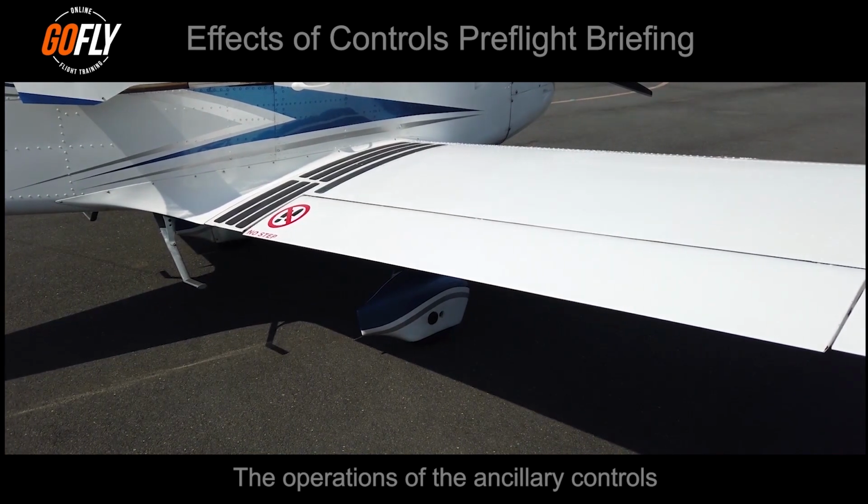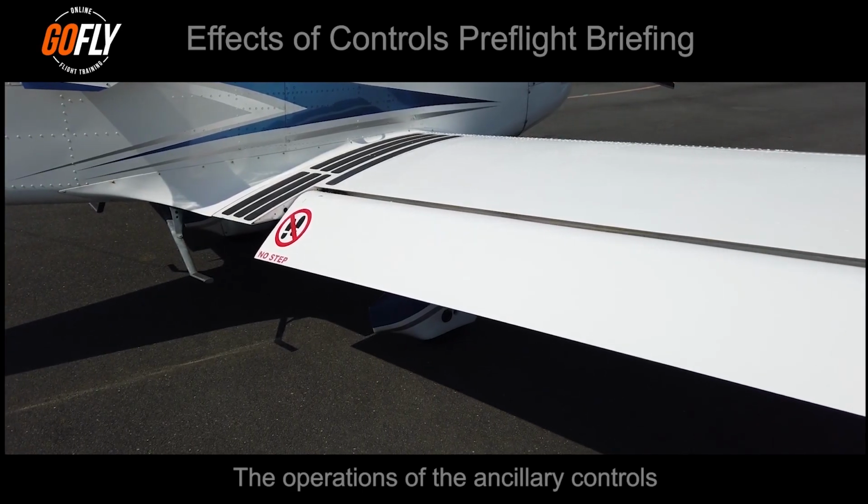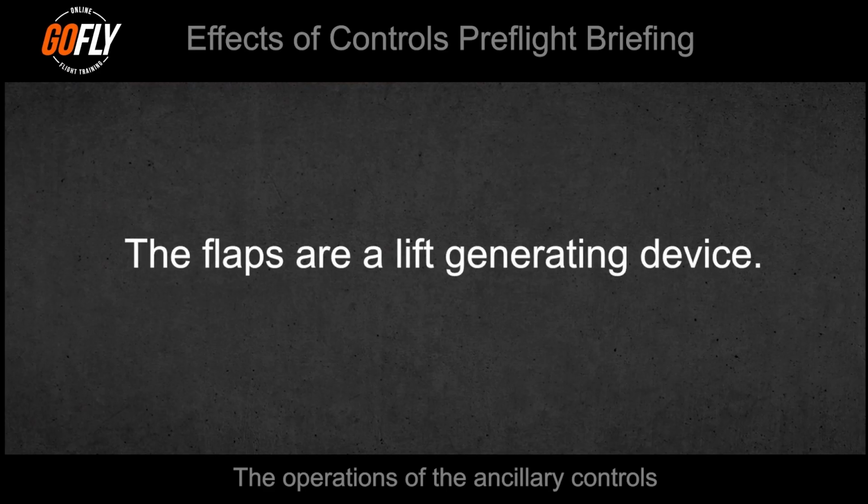When we select flaps, this increases the camber and thus increases the lift. Having flaps on an aircraft allows us to produce more lift and take off and land at a slower speed. The flaps are a lift generating device.